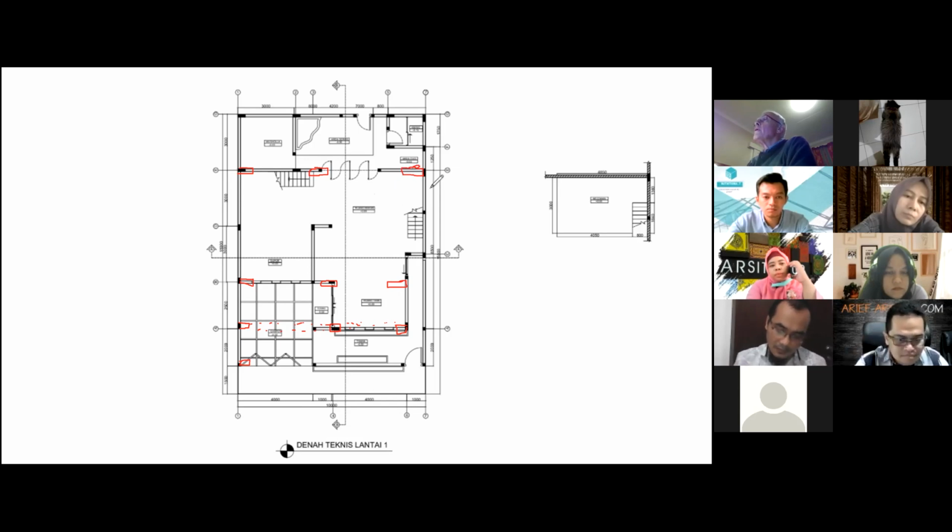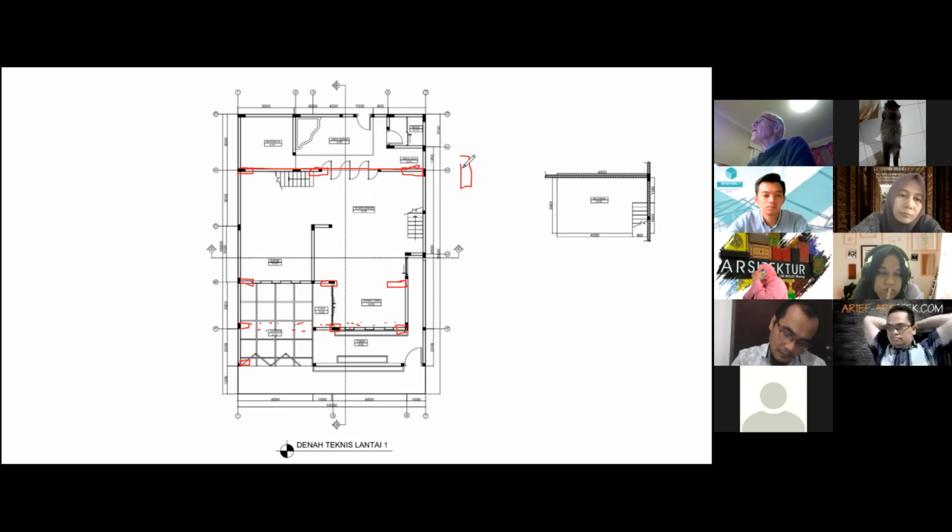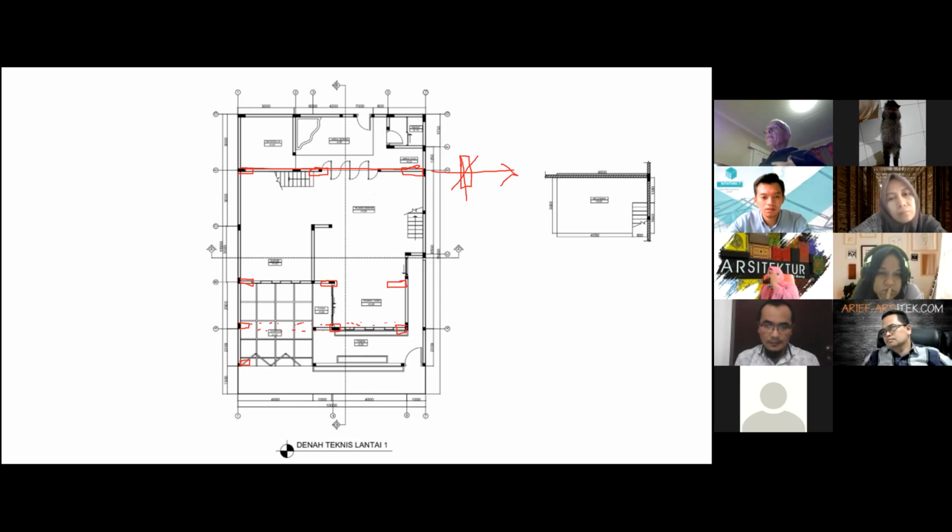But see how the columns have to be strong in the X direction. You cannot have a column like that against earthquakes in the X direction. This column is almost useless. So the student would have to do some small replanning of the spaces to accommodate this structure.